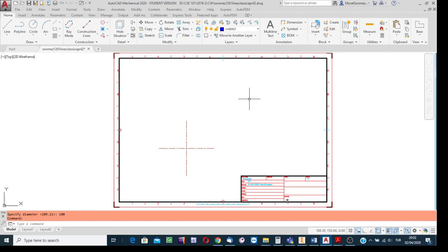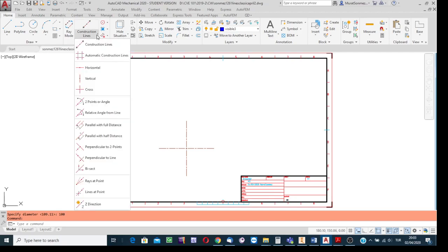Okay, answer the question using transfer lines. You know, my favorite method to mark the points is transfer lines. If relative to a certain point I need to mark another one, then use transfer lines. Okay, I dropped the list of the options. Shall I select the transfer line layer? No, no need. You see the selected layer is still the third visible outline layer. But I am sure if I use this tool, the created transfer lines will be created in the transfer line layer.